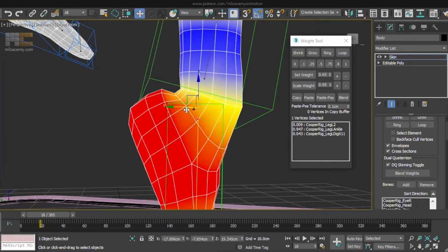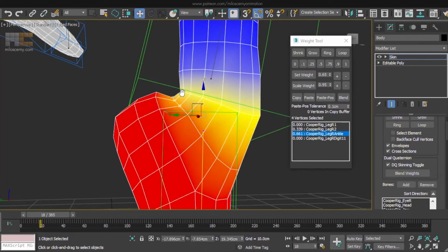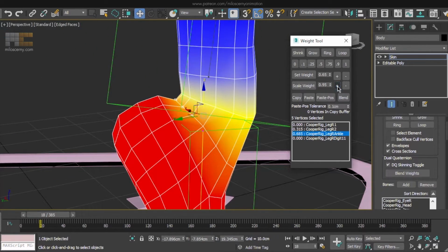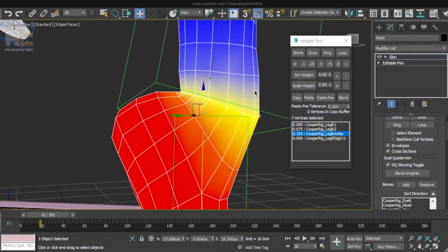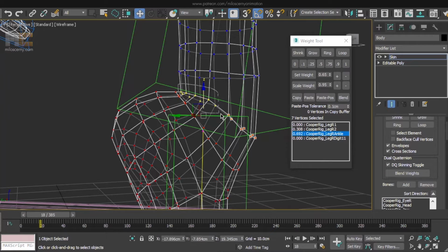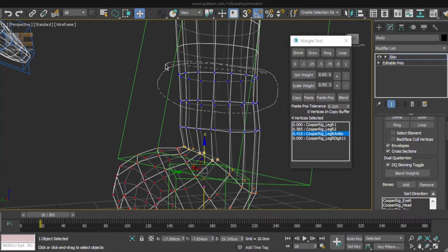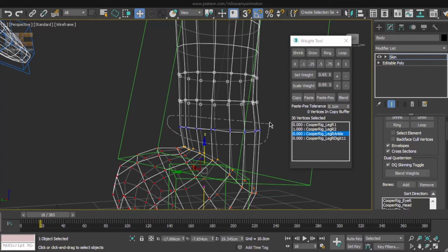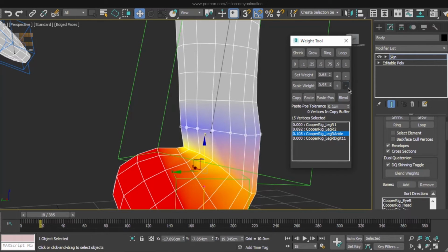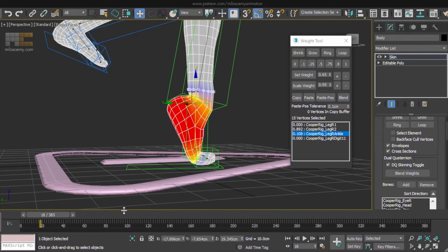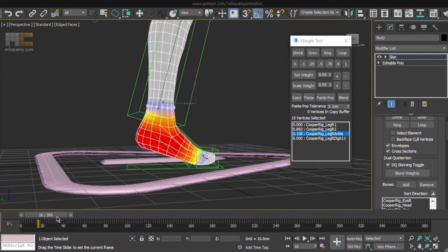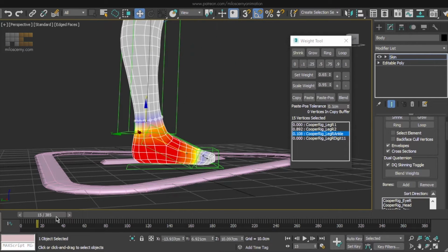Okay, we can immediately see that it's already better, but let's modify it a bit more. Like so. This front part more to the ankle. These vertices blend a bit more. These back ones a bit less actually. Vertices up here we don't need for ankle at all. And for this last loop, just some small value. Like so. So now the ankle bends pretty well, looks alright, and we can consider it done.